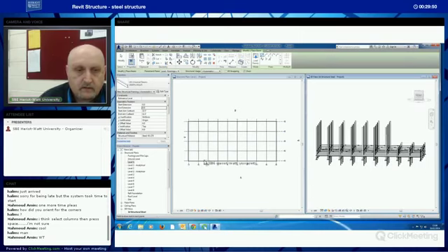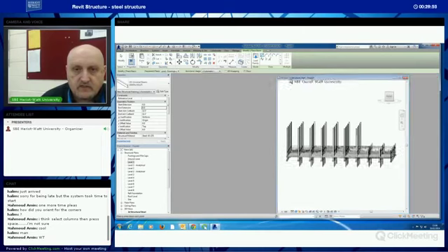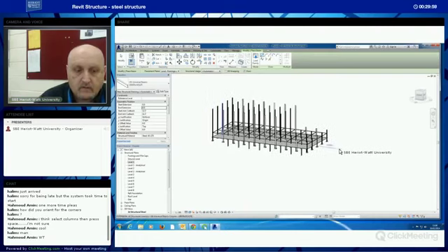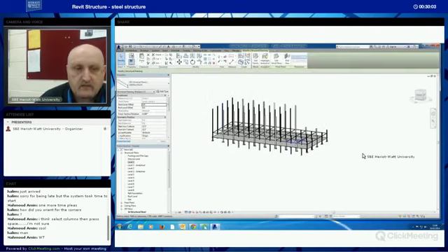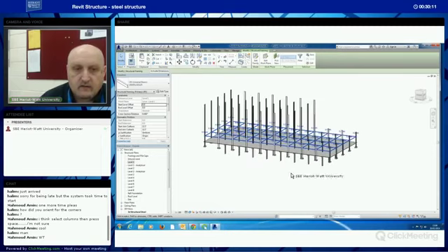Alright. So I'm going to close this one now. And I'm going to maximise this window. I'm going to select a single beam and then SA, so I select them all. Now I don't know if you'll remember that the thickness of our floors was 300mm, and these are going to be sitting in the same 3D space as our floors, and that's unacceptable.